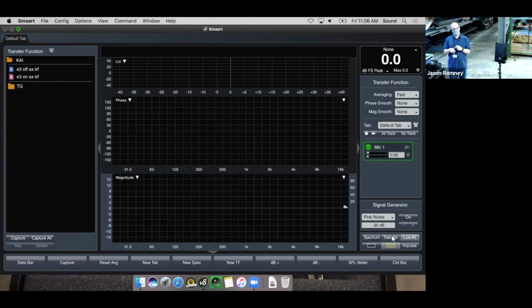And both Smaart and FuzzMeasure have the ability to load up a reference frequency response file. So you can load it up and say, here's the frequency response of the actual microphone I'm using for the measurement. And then Smaart and FuzzMeasure will compensate for those imperfections and not let those affect your data. Now, we are not in a situation where we're doing those kinds of measurements where we need that kind of detail, so we rarely will have the need to pull out actual reference files, but it's possible to do. So that's that microphone.